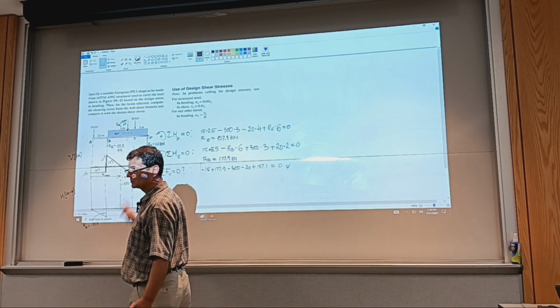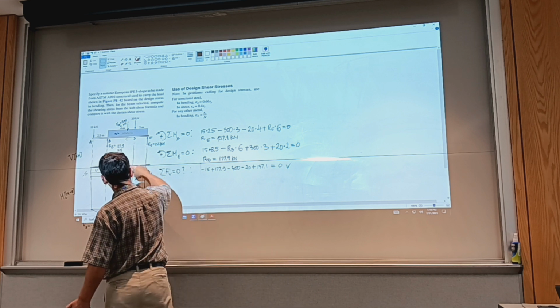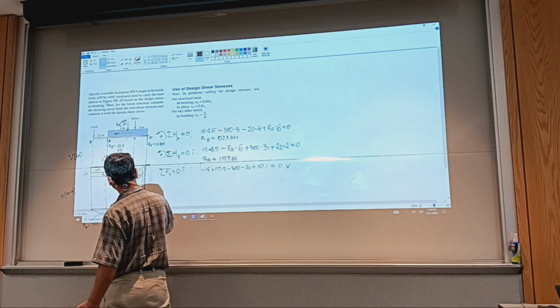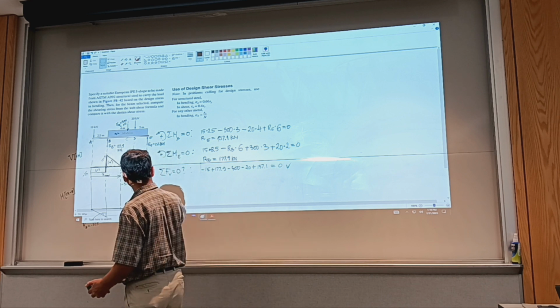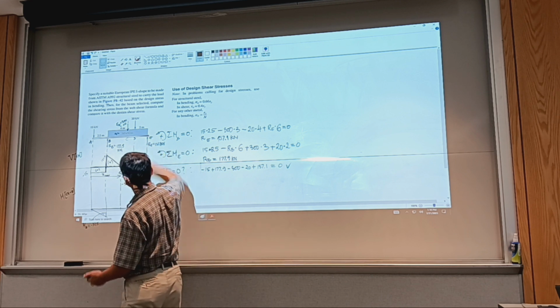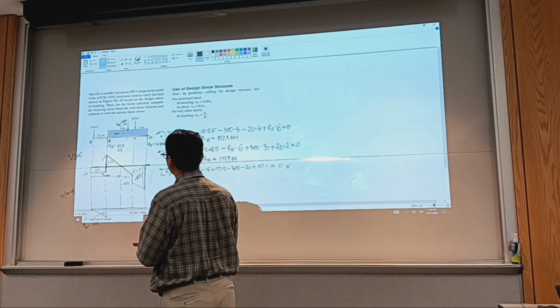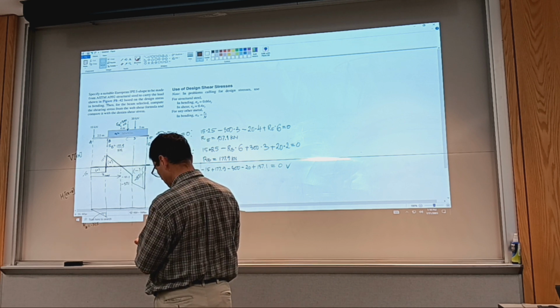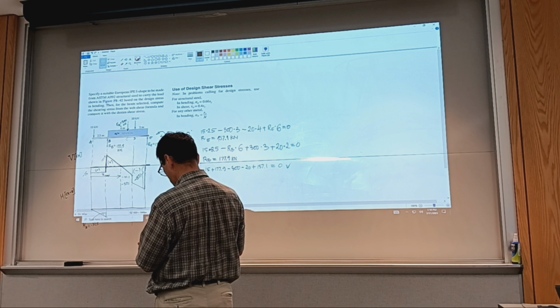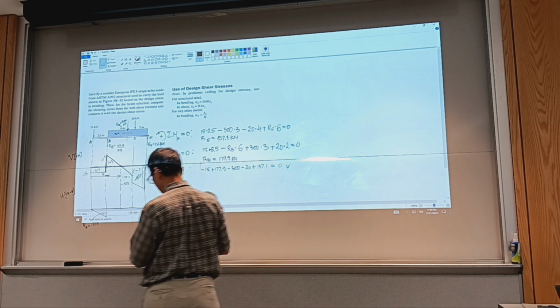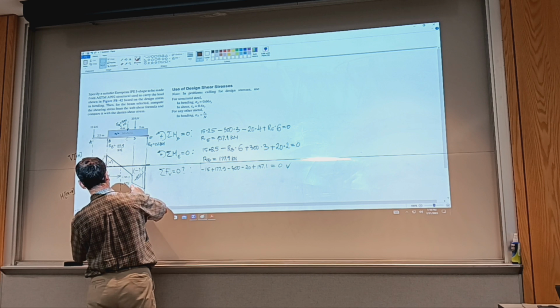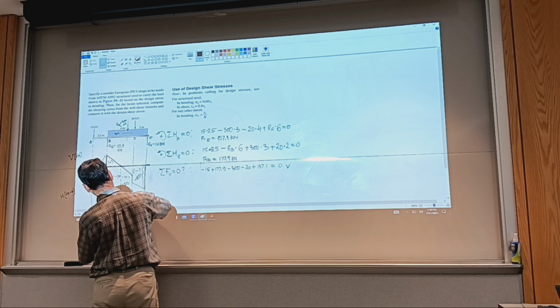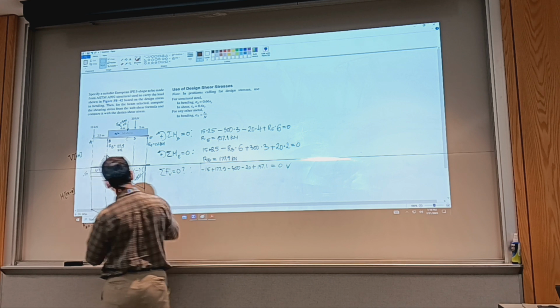Do you understand what I'm saying? So we go from right to left. The area of the trapezoid is going to give us the moment with a flipped sign, the moment at D. And the moment goes to 0 because I don't have any concentrated moments. So 157.1 times 2, that's 314.2. So it goes like here. So this would be the 314.2.